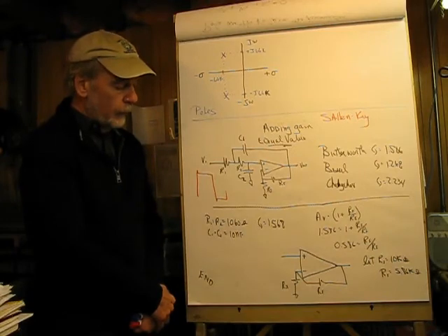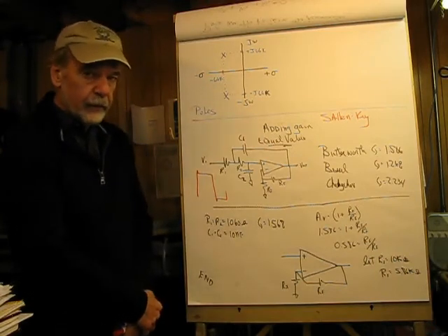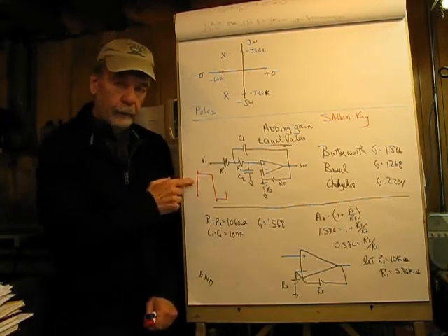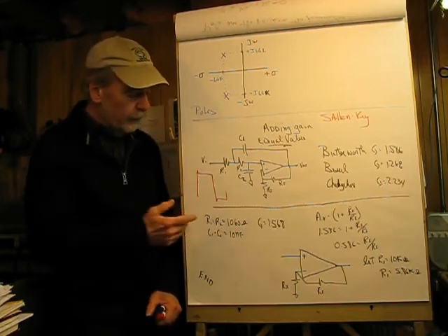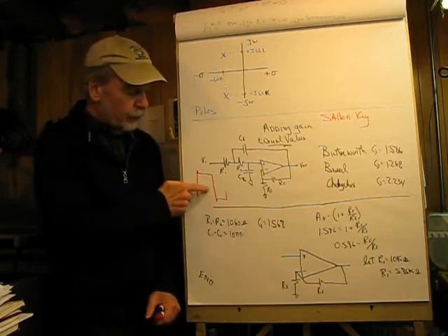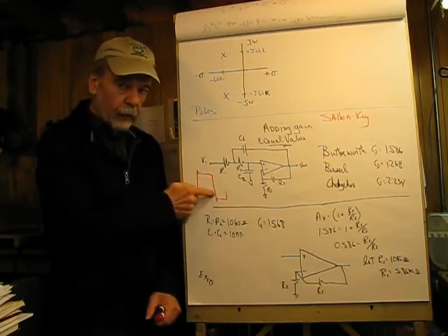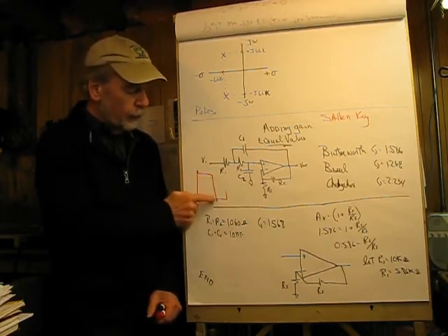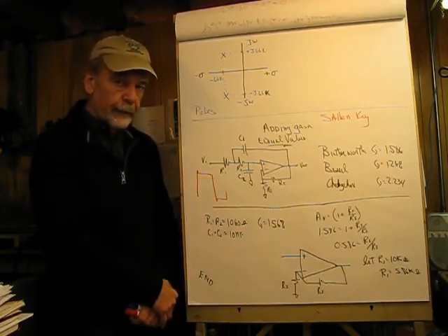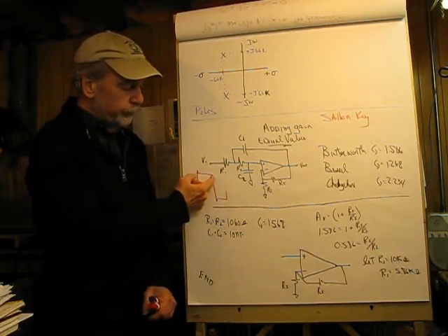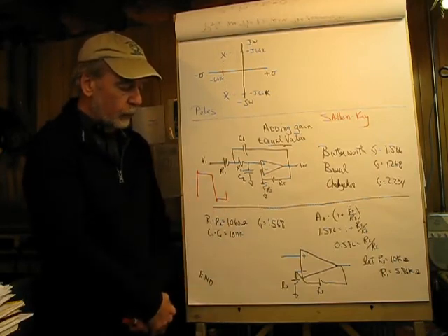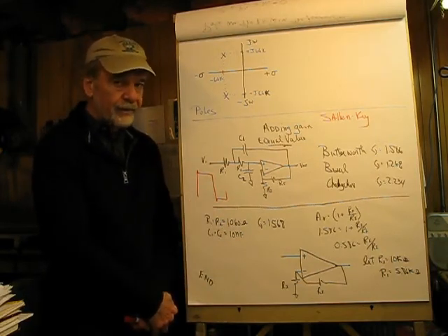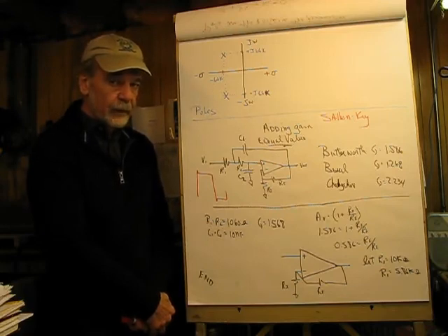If you're dealing with group delay issues, remember that a square or rectangular wave is made up of high frequencies on the rising and falling edges and low frequencies on the tops and bottoms. A square wave that comes through looking that way means you have good phase response.